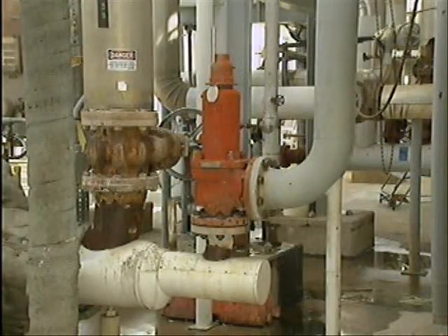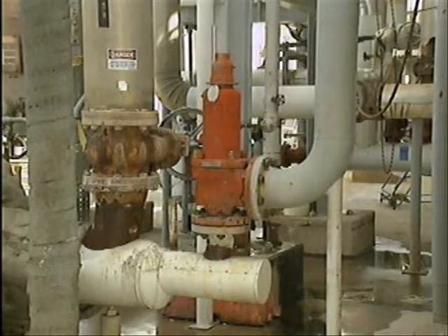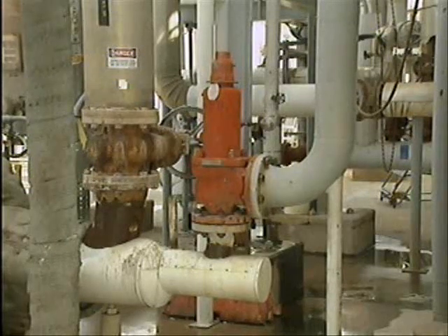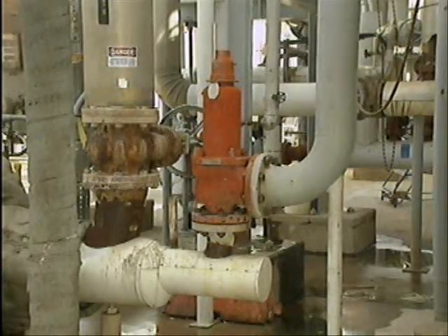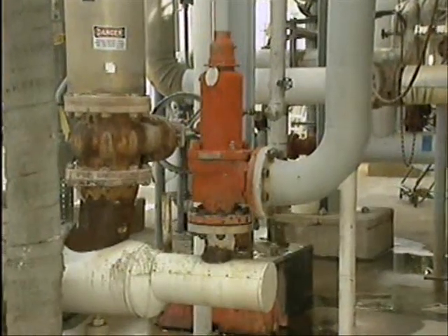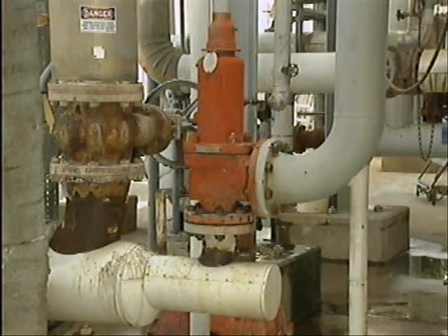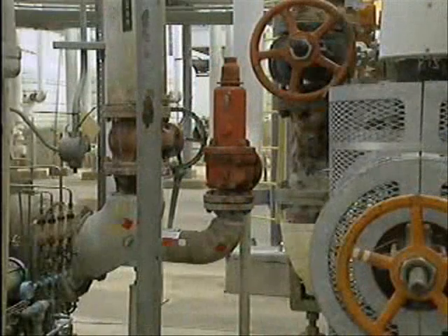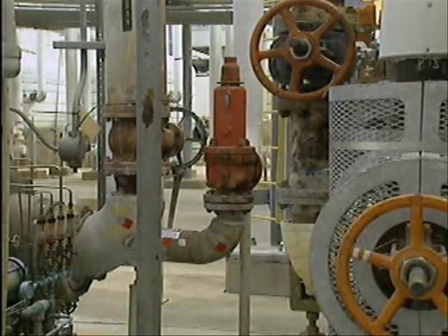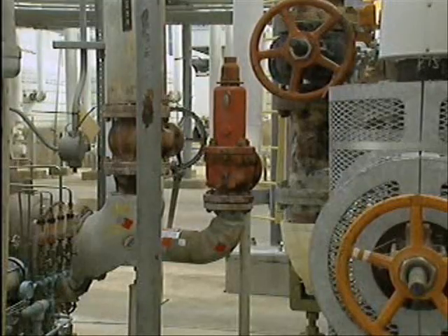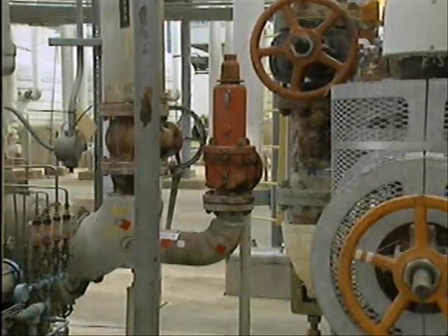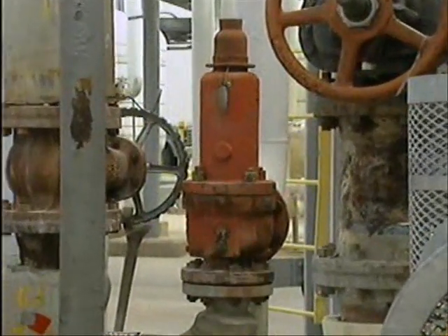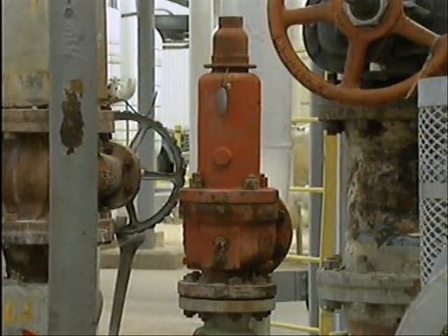While safety valves typically discharge gases or vapors, safety relief valves discharge gas, vapor, steam, or liquid to prevent a predetermined safe pressure from being exceeded. Safety relief valves are commonly used in refineries, on systems that contain liquid vapor mixtures, and in some low-pressure steam systems. Some types of safety relief valves are suitable for use as either a safety valve or a relief valve, depending on the application. For instance, certain safety relief valves can be used as safety valves on air systems and as relief valves on liquid systems.